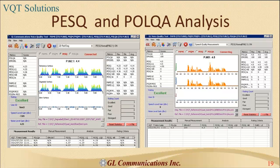The other thing we get with PESQ is something that I love, which is PESQ per utterance. For each syllable stated, you can look at the PESQ score. This will tell you if you have dropped voice within the call or dropped packets or what have you. POLQA doesn't offer that because it's basically just one single sentence. So you do get some features in PESQ that are not offered in POLQA. That's why I still like to see the PESQ. But the answer to your question, Shelley, is yes, POLQA can be used for both narrowband and wideband, older networks and the newer networks.